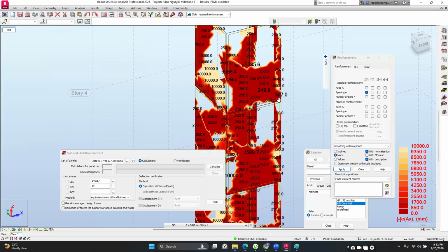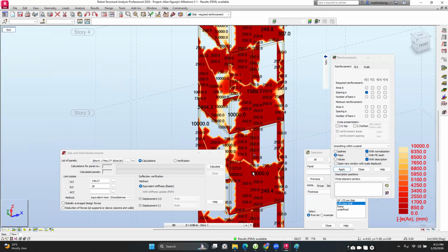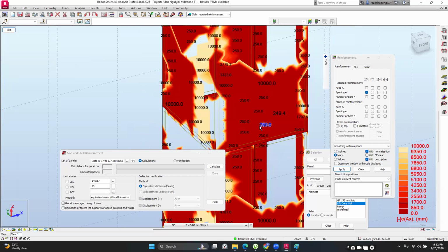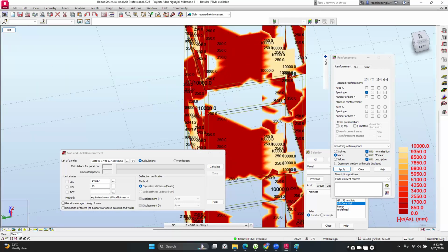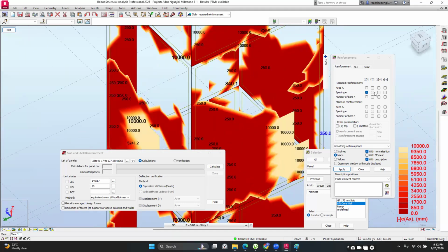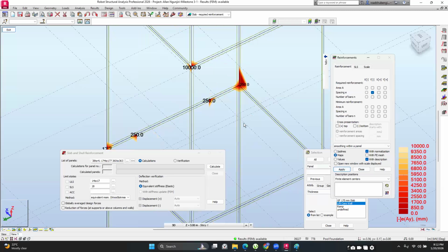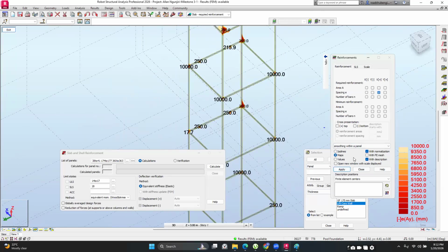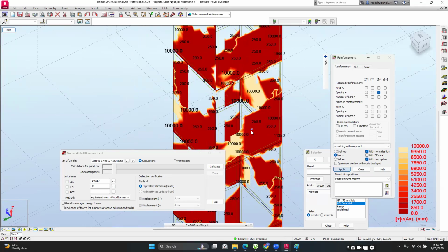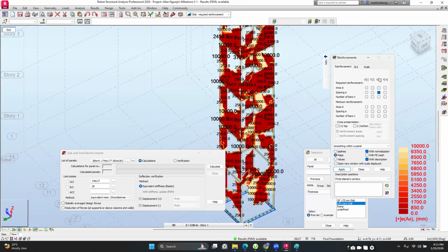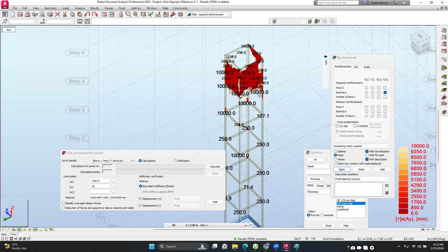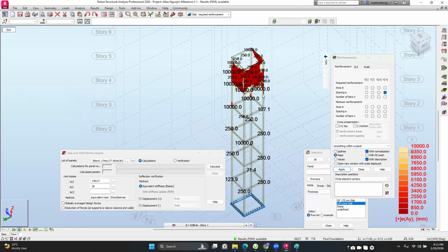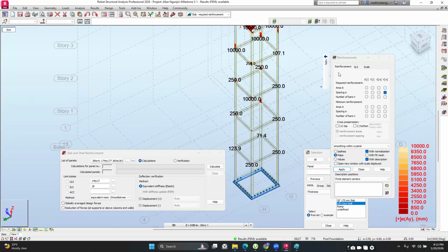Okay, so check the spacing. You can see you majorly have T12 bars at a spacing of 250 millimeters. It does not make sense to space them at say 10,000 millimeters for this point. So you always go with the smallest spacing that you have. So if you have 250 millimeters as your smallest spacing, you are going to have that spacing right there. Okay, so that's how you design for these members in this manner here. All right. So this is method 1.